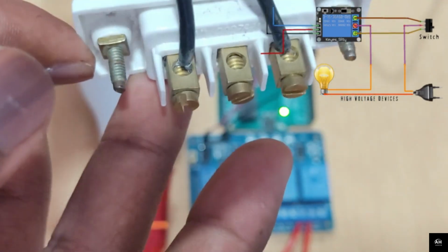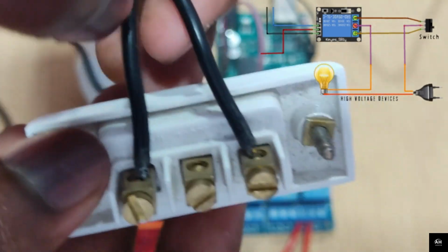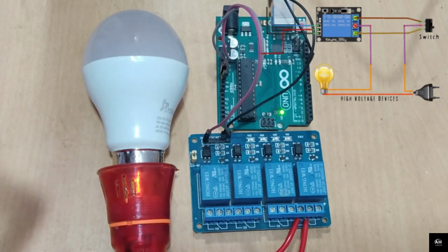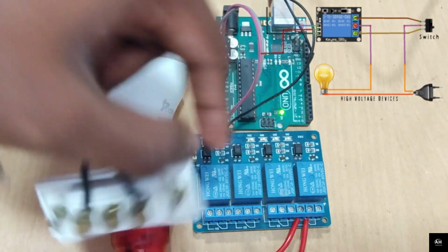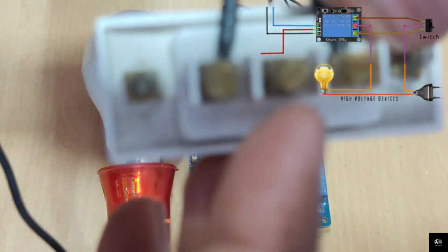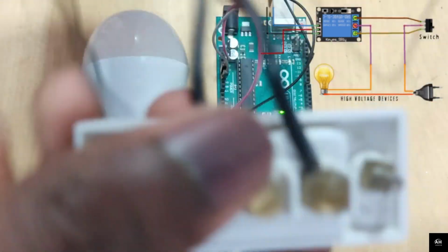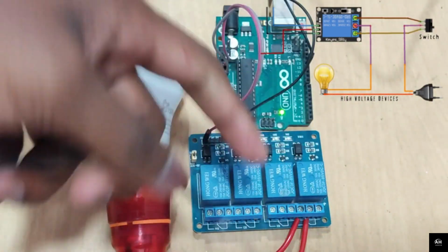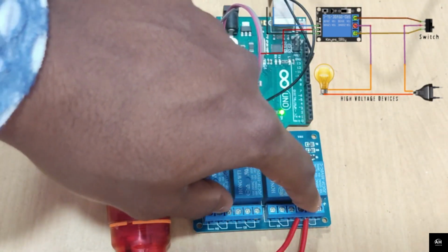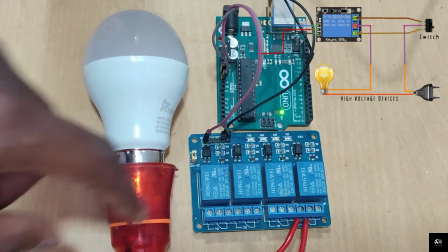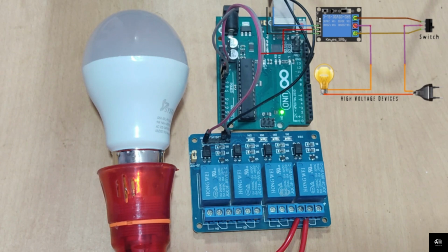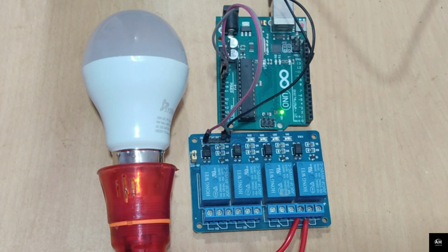So you can see it has basically three inputs. So these two inputs will go into the relay module input, where we have basically, you can see on the screen that it has three inputs. So we will just remove this last one and we will connect it in the middle of this two-way switch, and these two wires will go in these two connections, the first one and the last one, and the middle will be connected from this bulb. So I will just try to remove the last wire from here.